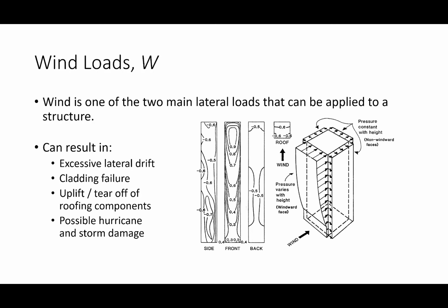To put things in perspective, if I were designing the second story floor beams in this building versus the fourth story floor beams, the floor beams that are subjected to gravity loads aren't really going to behave any differently on this story than they are the story above us. They're pretty much going to be the same beam. In other words, if you have a building that has repetitive floors, under gravity forces you have the same span, the same loads, the same bracing configurations, it's going to be the same thing. Okay, that's not the case with wind loading.